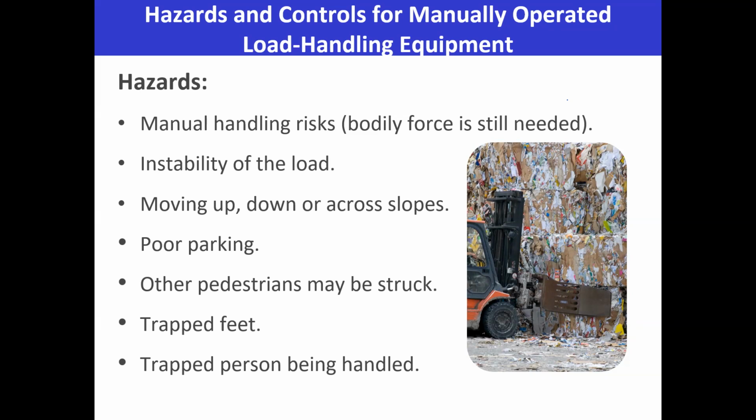That is why whenever we are using load handling equipment, forklift trucks, etc., we must always provide segregation between pedestrians and vehicles. If you keep them together, definitely there will be an accident. So pedestrians and vehicles should be separate. Trapped feet can be an issue with boom trucks as well, and with other load handling equipment.